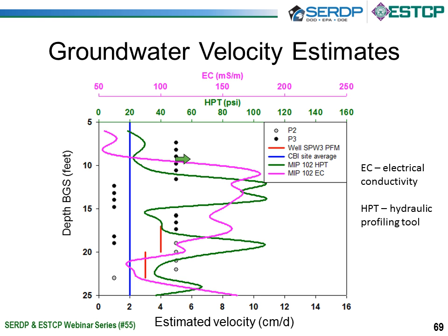And then the hydraulic profiling tool. So the electrical conductivity varied a lot, but unfortunately, while it should have related to the grain size, the salinity at this site changed so rapidly, I'm not sure that that result is very meaningful. But the hydraulic profiling tool, which is related to the pressure it takes to push water into the formation, basically indicated 3 relatively significant peaks.